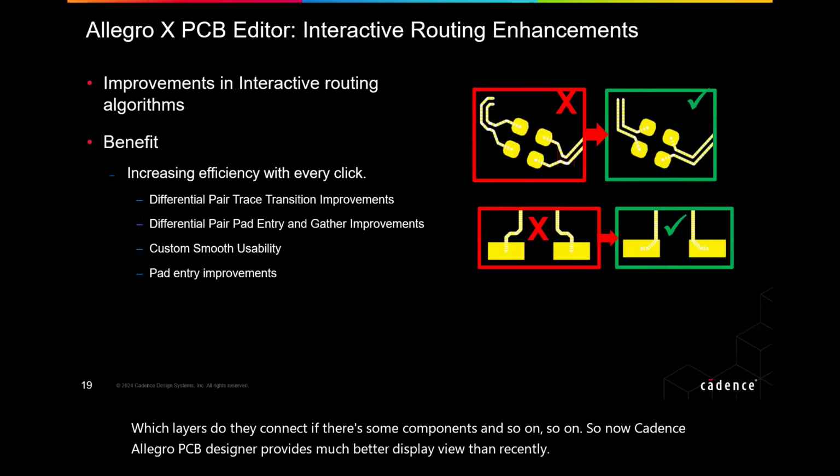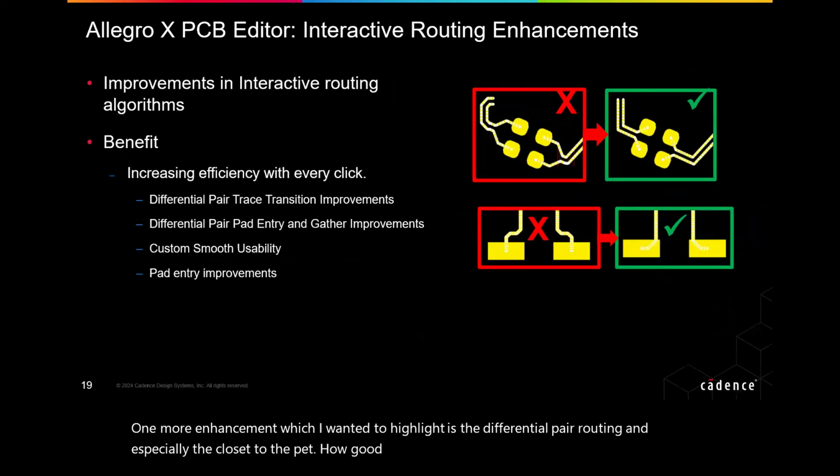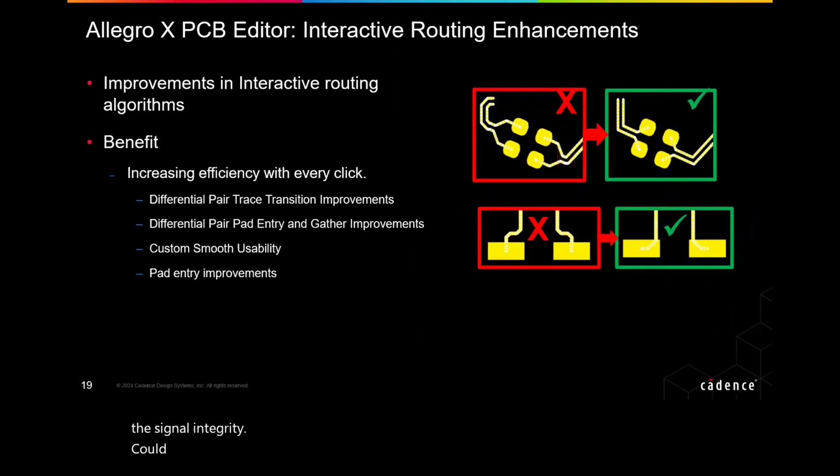One more enhancement which I wanted to highlight is differential pair routing, and especially the gather to the pad, how a differential pair automatically comes to the pin, so that the signal integrity is not damaged because of this gather point. It's much smoother and much more improved recently.